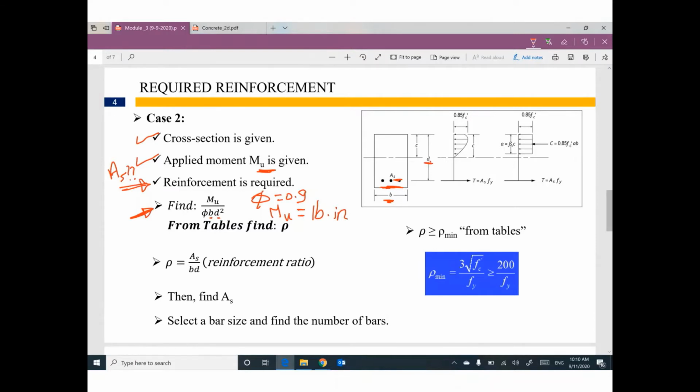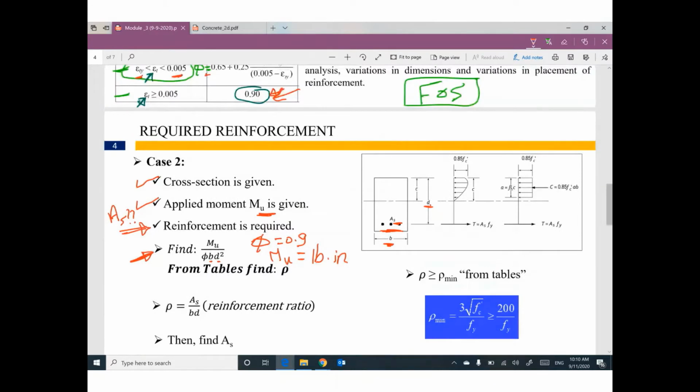In pound inch. All the time we convert from pound inch to something else. No. Right now, if you have something else, please go ahead and convert it to pound inch. For example, if your moment is in pound foot, you need to multiply it by 12 to get pound inch.